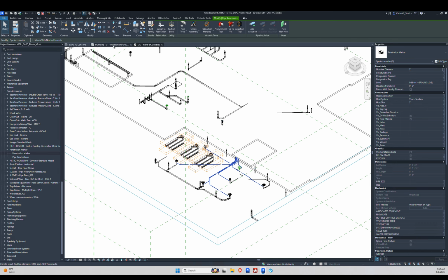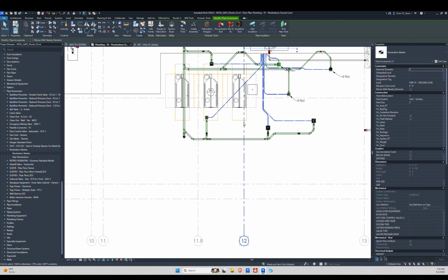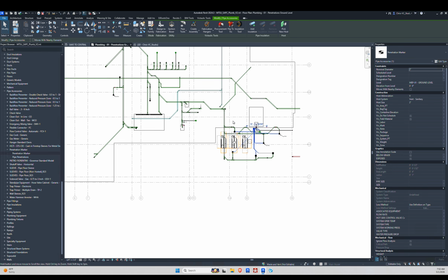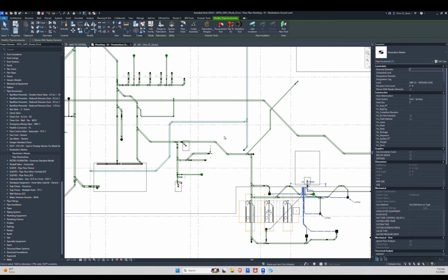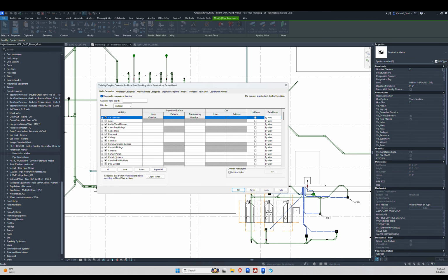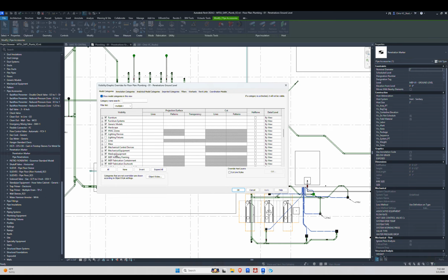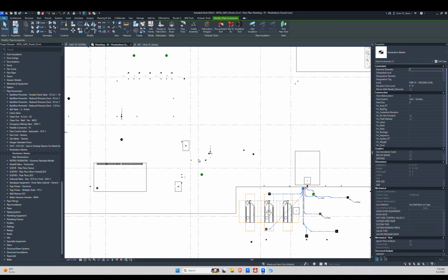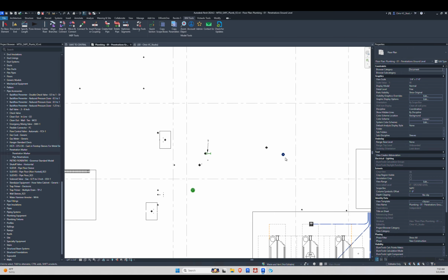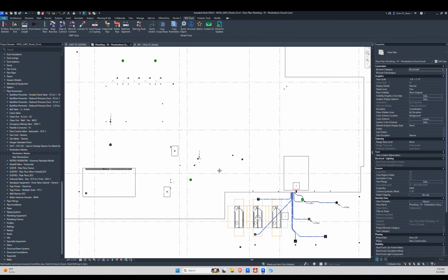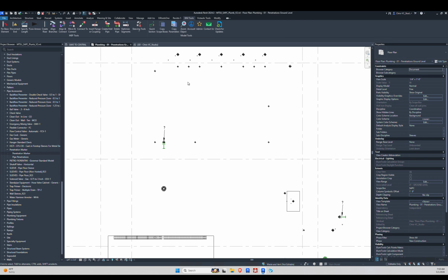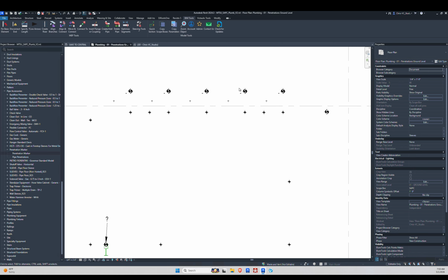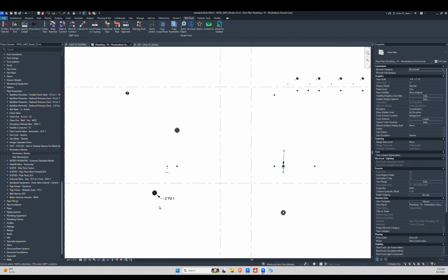So going back to the floor penetration. So now I got all these pipes and everything showing, and all I want to do is just show the penetrations. Now we'll just go to visibility graphics. We'll come down here, we'll turn off our fabrication pipe work. And now all of a sudden we have every single penetration showing where everything was turning up. We have floor drain still showing,